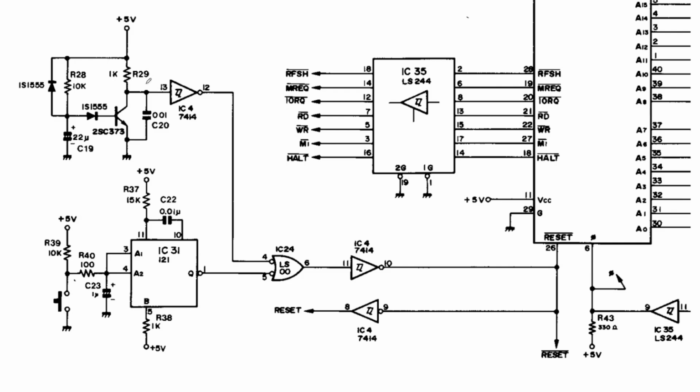If we go back to the circuit here on top, this here is just the reset timer, which makes sure that the CPU is reset when you start the computer, but then a fraction of a second afterwards it comes out of the reset state. The way it works is the following. When you start up the computer, this capacitor here, C19, 22 microfarad, will be discharged.